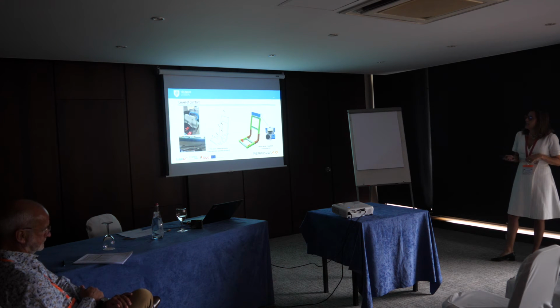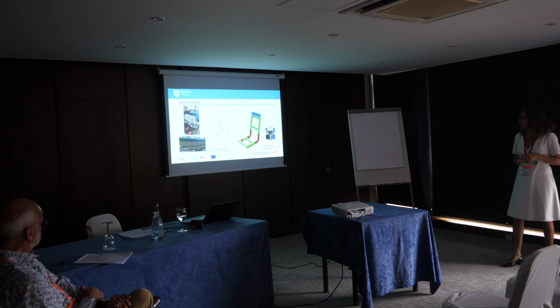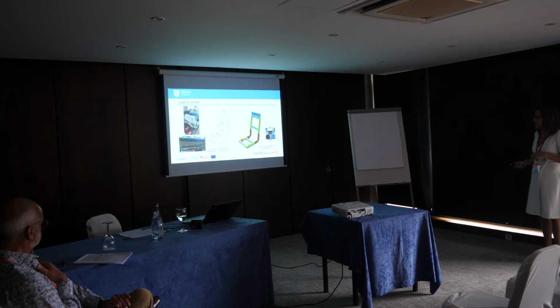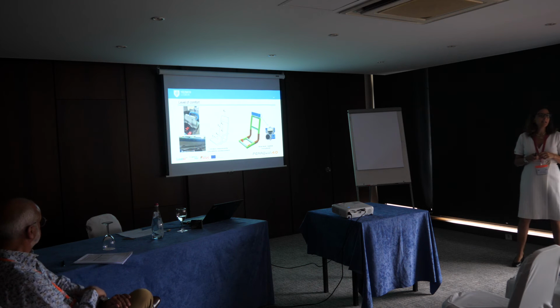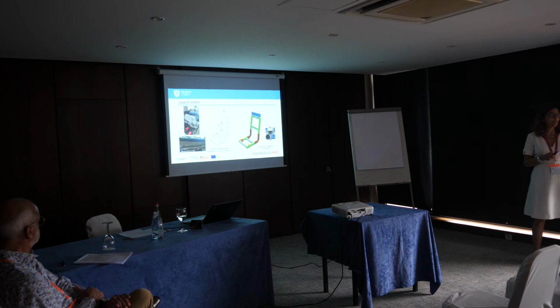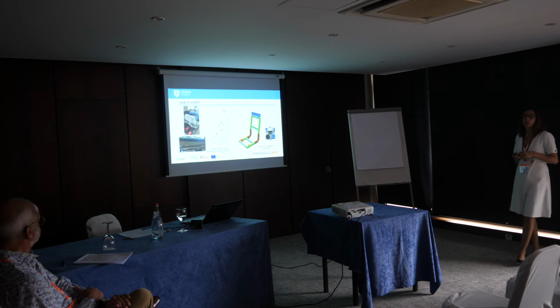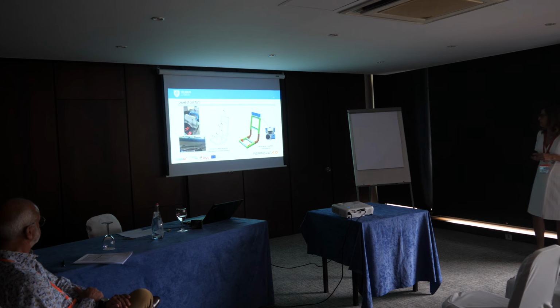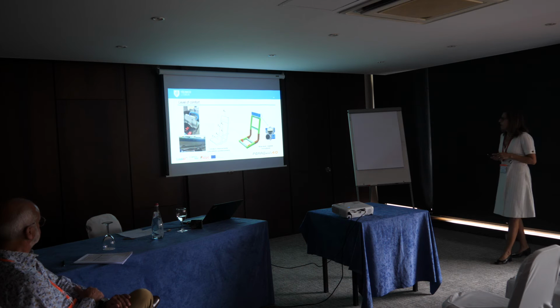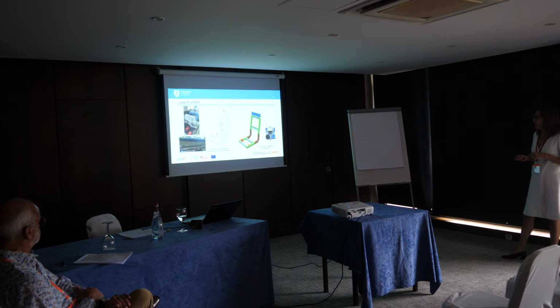The second type of sensors is accelerometers, and we will connect accelerometers in these directions and locations, and here we will perform experimental tests in labs, and after this in service conditions inside the train. And finally, for the comfort of the passenger, we will connect a microphone in the headrest to obtain the noise level.